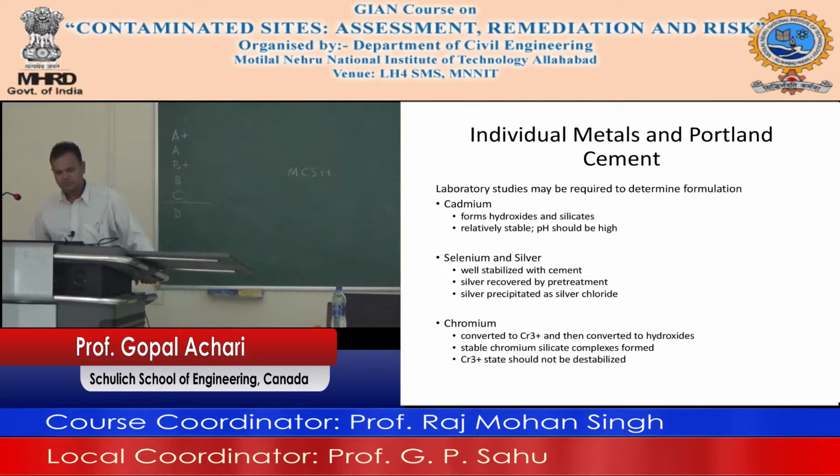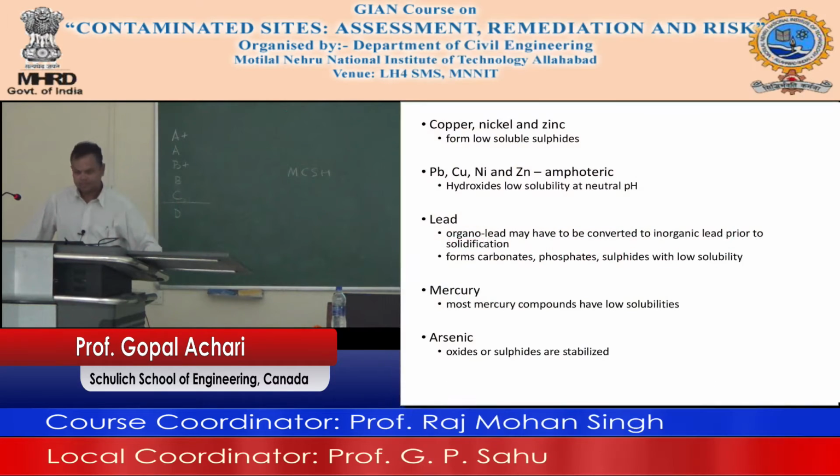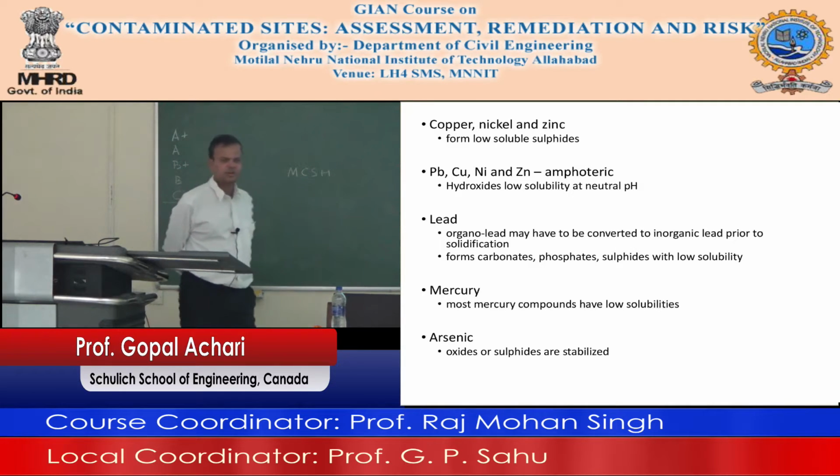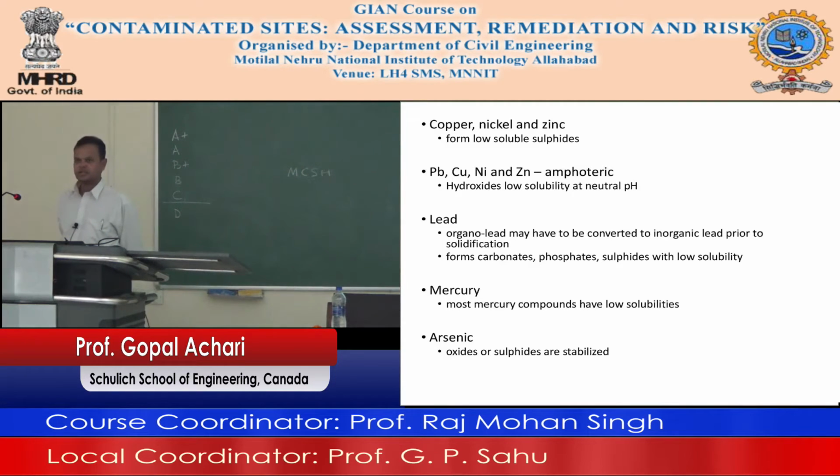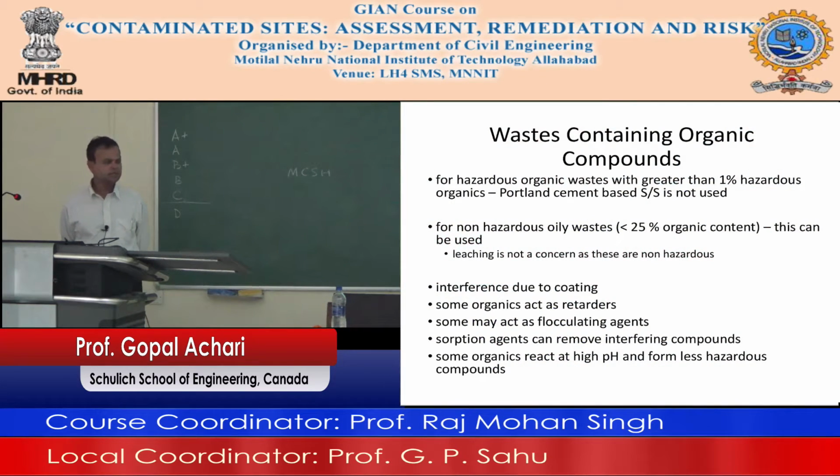Copper, nickel and zinc form soluble sulfides. Lead, copper, nickel and zinc are amphoteric. Amphoteric means they are soluble at high pH and low pH. The hydroxides form. So you can use cement for all of this, including lead. Cement is quite widely used for different types of metals. So if you have a metal contaminated site, think cement and cement based material. Maybe that might be your solution.